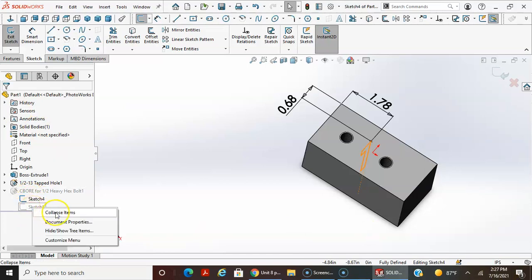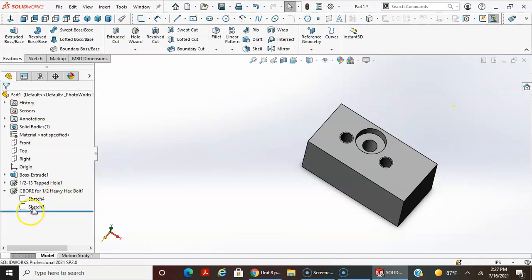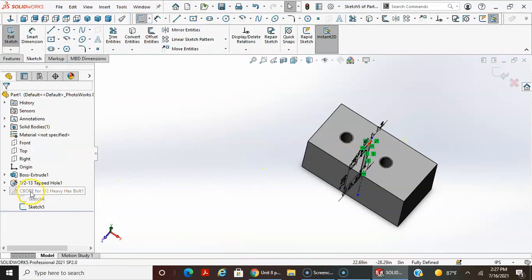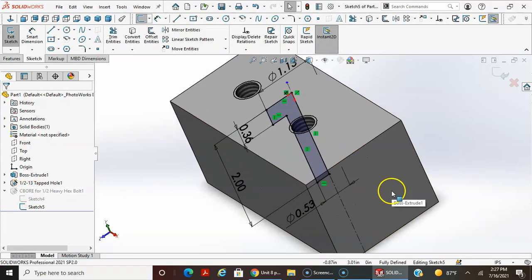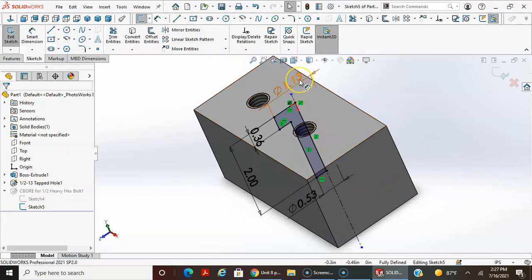And again, I'm going to exit that sketch, and I'll open the sketch of the profile that's defined within the property manager. And again, it shows the counterbore diameter, counterbore depth. This shows the through hole depth, but it goes through, so it's exactly 2 inches. And then it shows the through hole diameter. So hopefully that helps, and that's a little concept video on the Hole Wizard.